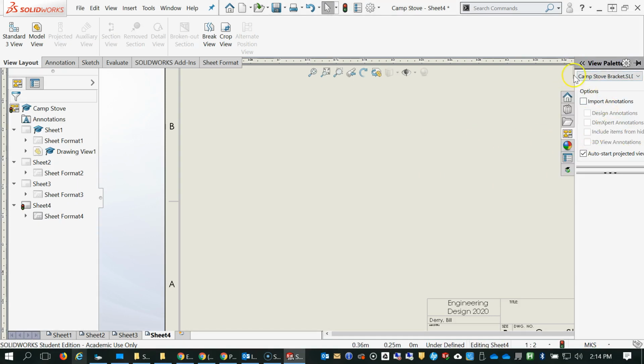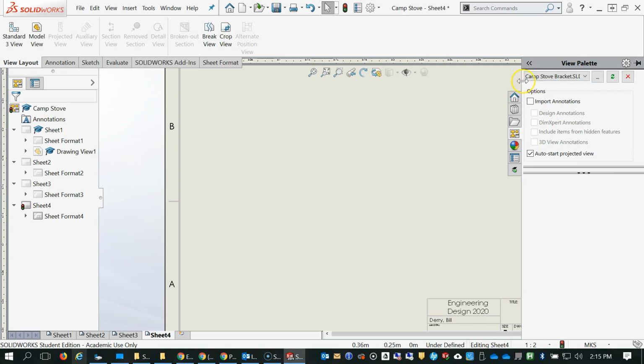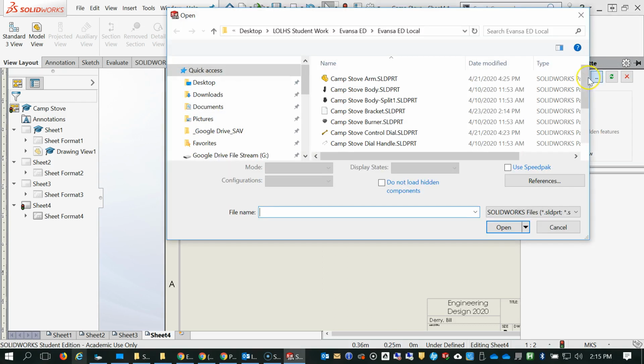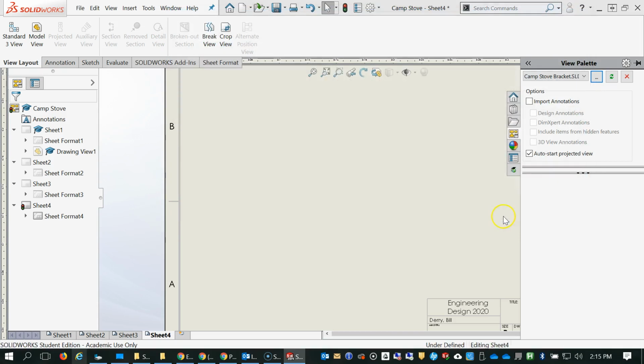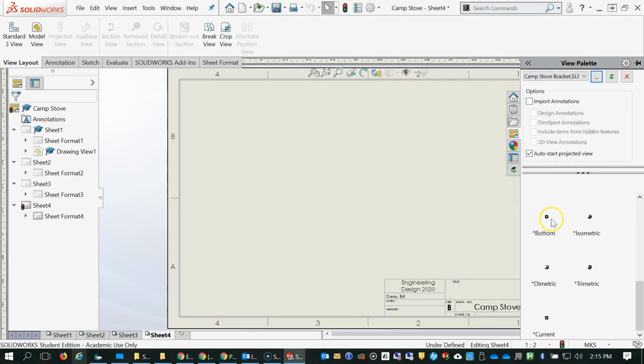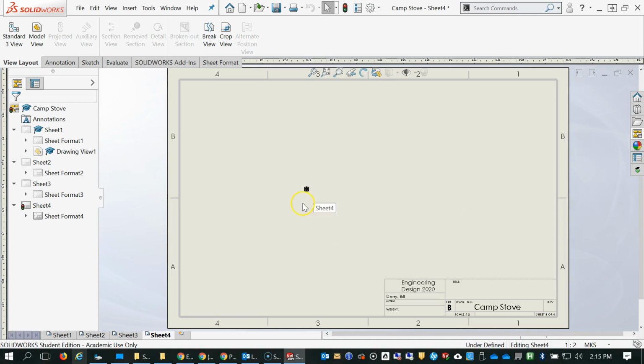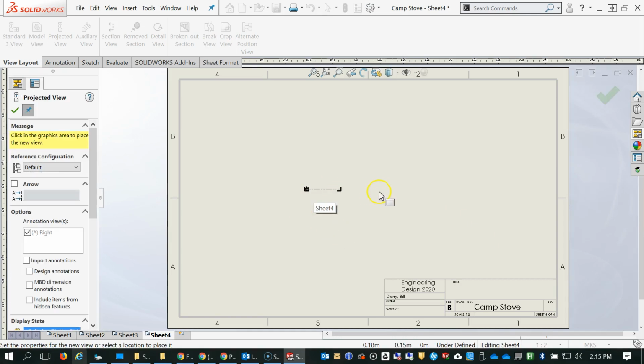So there, hopefully you drew your parts in the correct orientation. You can change them after the part, but let's just see what happens now if that part is updated. So this says the front view, and if I project out, yeah, that's what I wanted. Okay, so I did get the change I wanted.